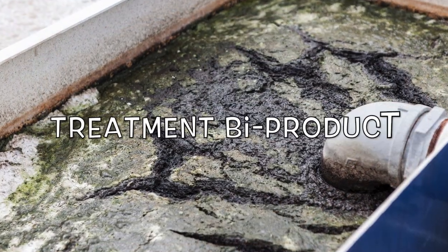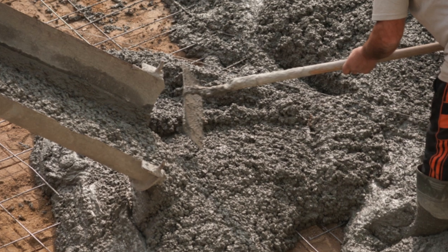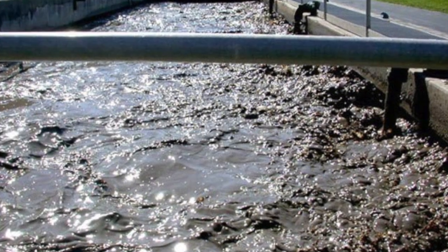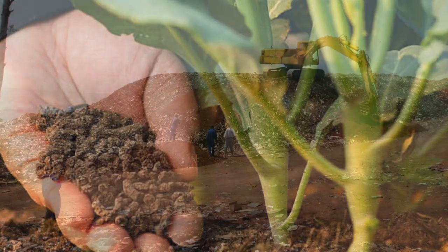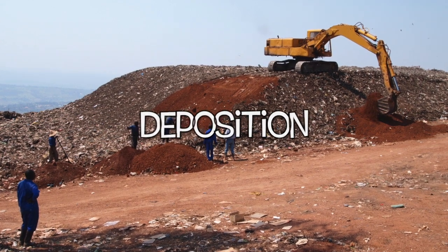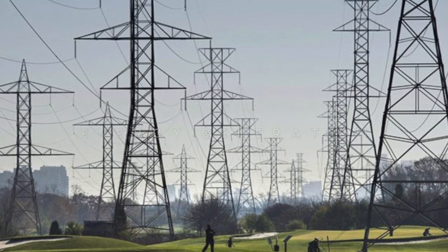Sludge is a byproduct from the treatment. The tank is not only acting as a storage for the sludge solution, it also blends and thickens the waste-activated sludge, primary sludge, imported sludge, and scums before further processing. The final disposal of the sludge is as fertilizer, deposition at waste disposal sites, incineration on site, and as part of energy generation.